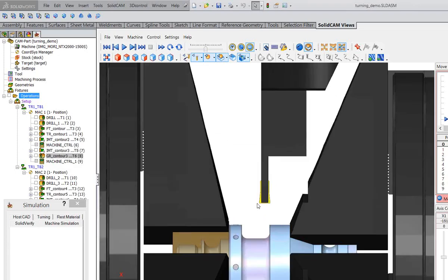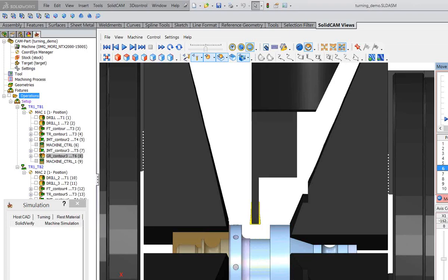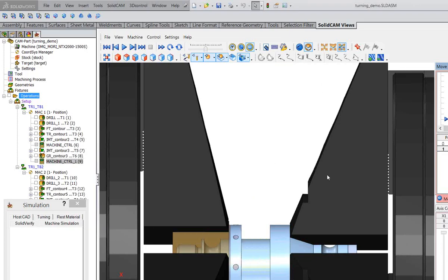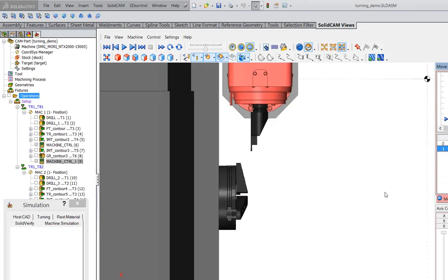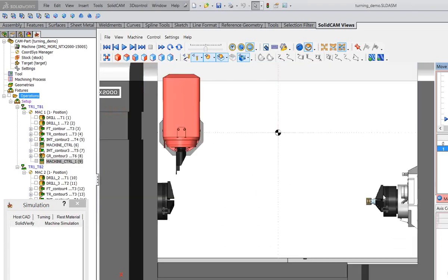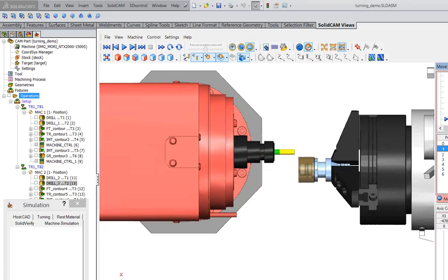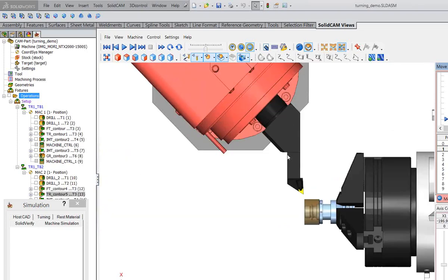Now I will finish the groove, the grooving finish operation, down only technology. Retract, take the part to the subspindle reference, continue to work on the opposite side. Drill, face, with the same tools, with different spindle orientation.